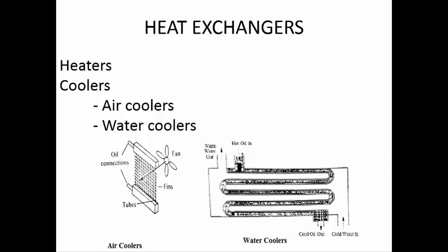So whether heater or cooler, the main idea is to maintain the proper temperature of the oil. If the temperature of the oil is right, its viscosity will also be at the required value. Only if the viscosity is at the required value will we say that it is operating in a very efficient manner. Otherwise, you will have a lot of power losses.